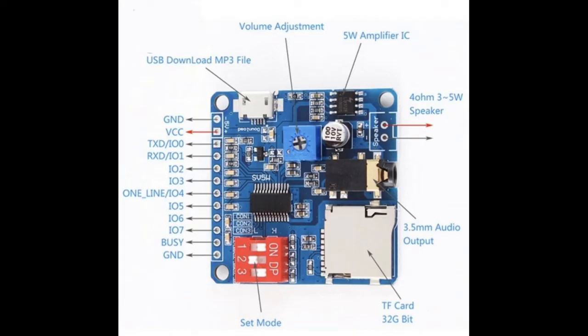The MP3 player runs on 5 volts, which is normally regulated down from the plus 15 supplied by the control card for the demand pot circuit. Since for this test the control card is not present, the voltage is borrowed from the sound system power supply via a test hook.